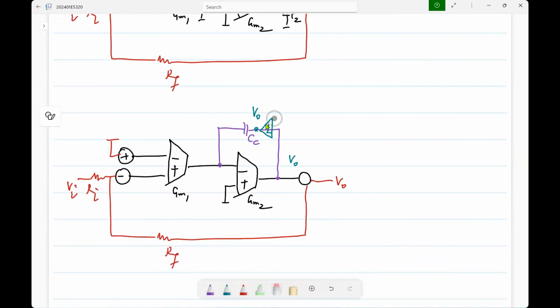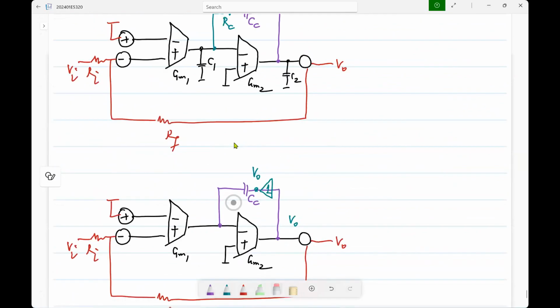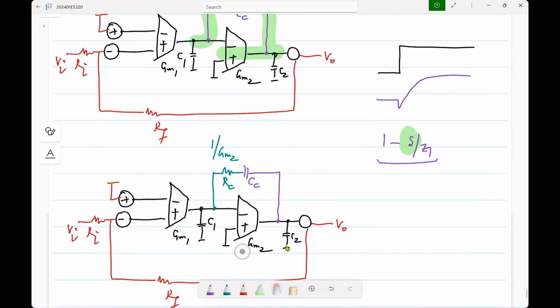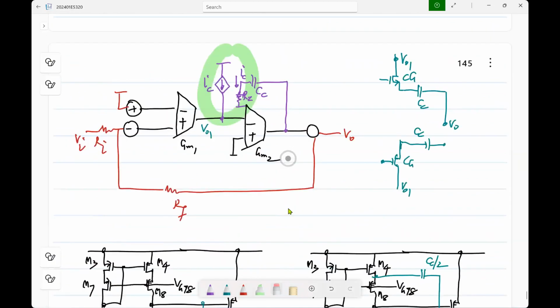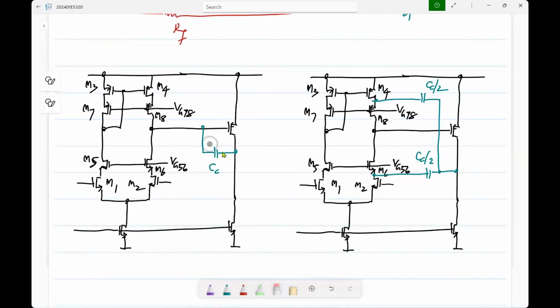This one was not implemented, right? I'm talking about the transistor level assignment. In the ideal case, of course, all of them work. In the transistor level op-amp, you have a telescopic cascode first stage, right? So what I had asked was to try and connect this here and there and see what the phase margin is. I don't know if you tried that. If not, try it out and see.